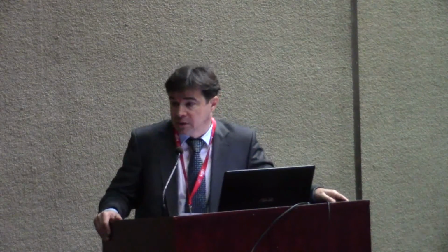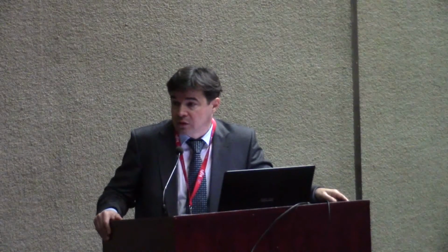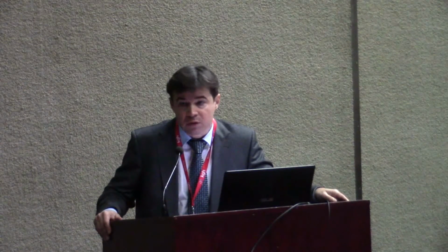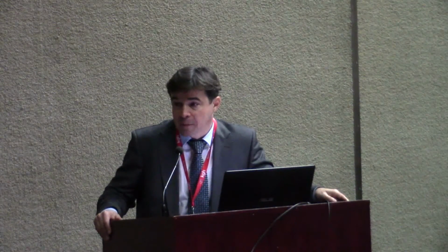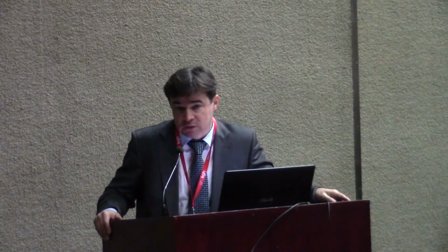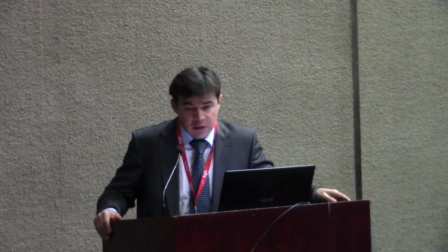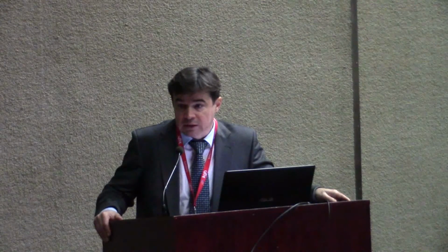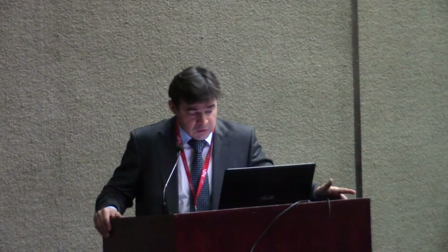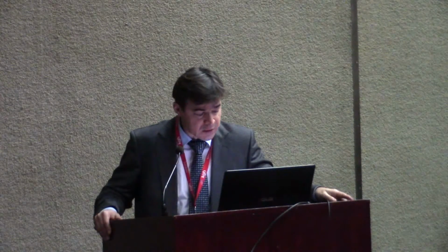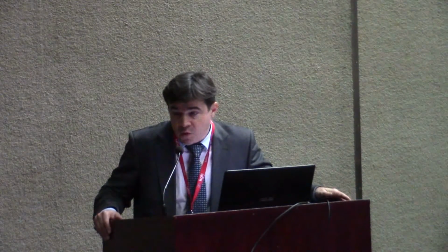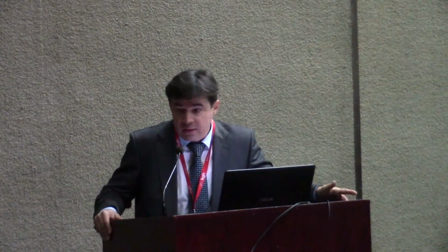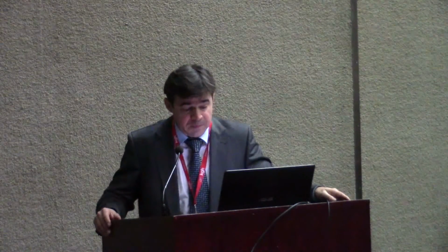Vaporized water condenses on the outside wall, and if the climate conditions are very severe and the outdoor temperature is cold, it can bring about deterioration of the construction. Also, the consequences are the following: generation of mold, metal construction corrosion and degradation of air quality in the space.